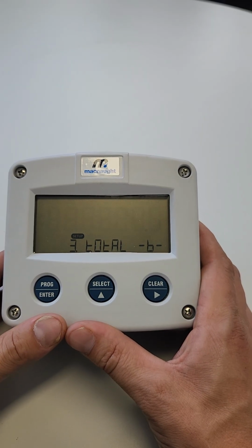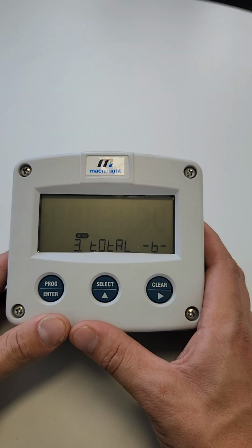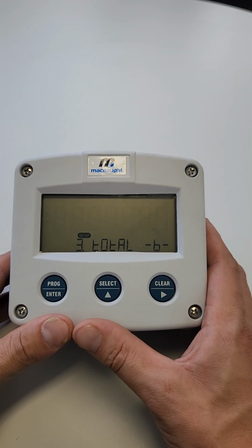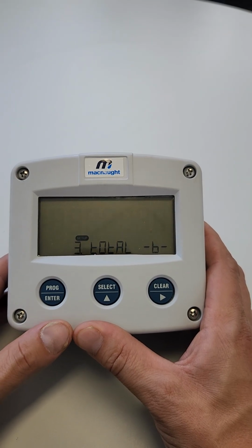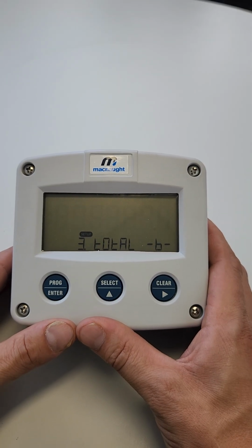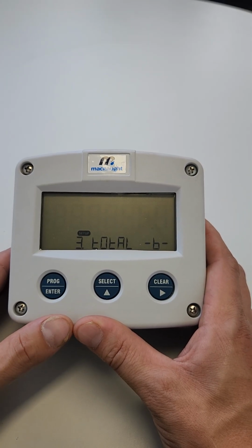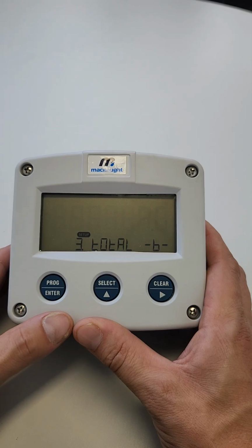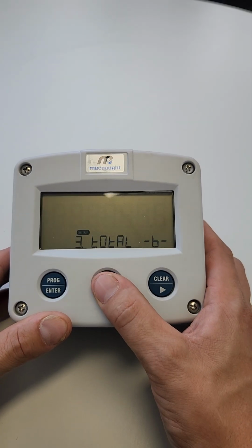So make sure you remove the pulse cap and check your K factor on the meter, or the fuel meter, or the light vehicle and the bulk diesel meter that you're entering into the display. I'm just using these figures for an example. So we'll use 52.19. So number 3, total B.